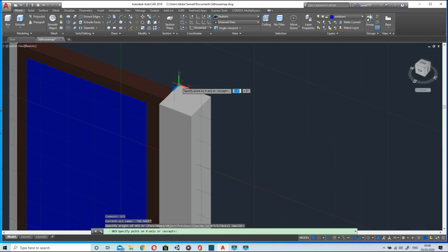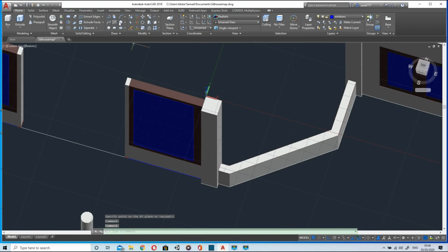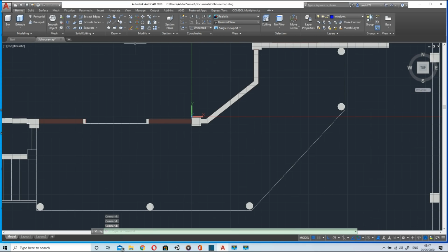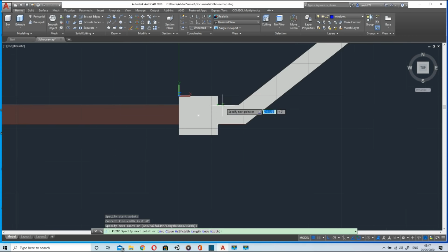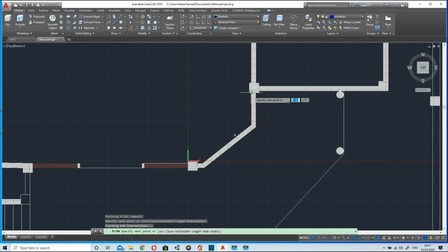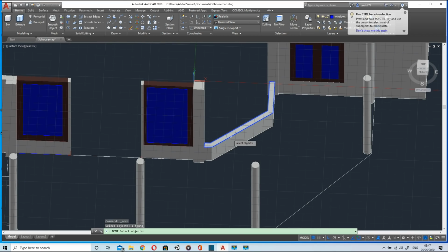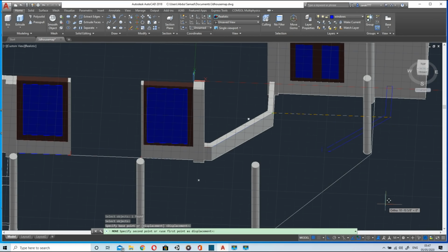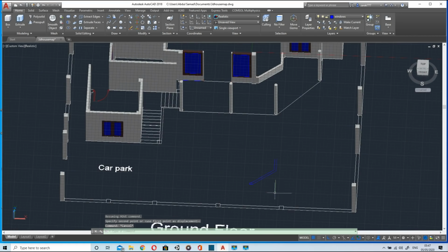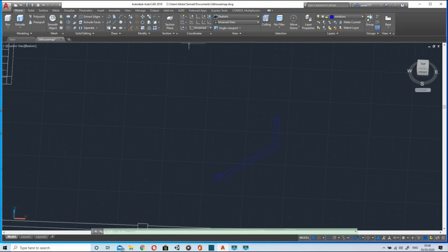Now we will place UCS over here. Move the line in this pattern. Okay. Now we can move this line or cross section from here to an open space, and now press pull this up till your required height.